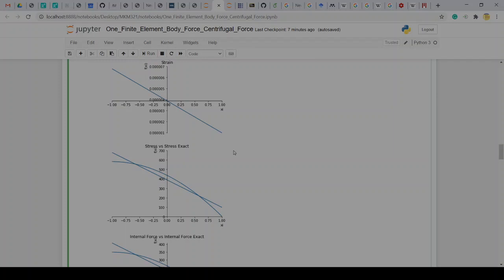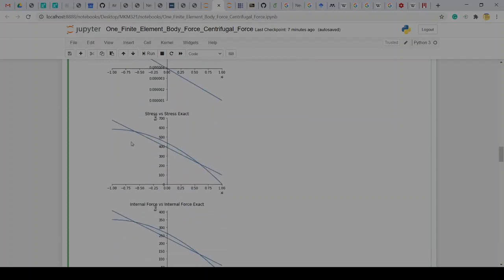Okay, so then when we start looking at the stress, this is a straight line. Again, strain is straight, so the stress must be a straight line, because the Young's modulus is only a constant. With that straight line stress, we can see that at the end, at psi equals 1, the stress is not 0. Although that is the end of the bar, and there's essentially no additional material pulling on that edge. There's no traction at that edge of the bar. But in the case of this solution, we see that there's indeed a traction acting there.